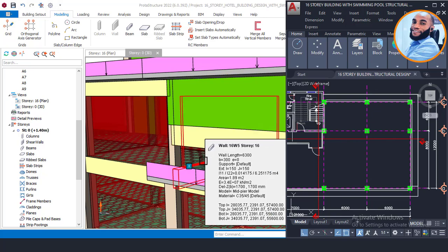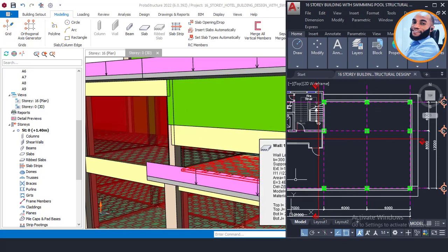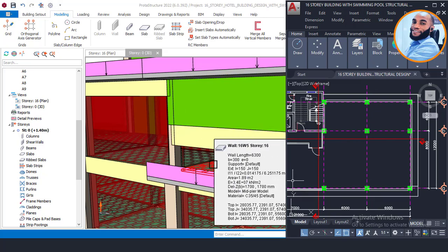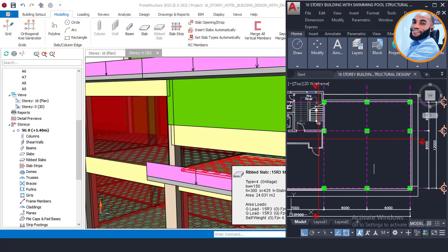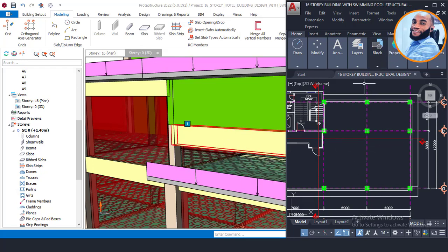So this drop down or this headroom has no issue because it is just a free walkway, and this headroom is around 1.9 meters or thereabouts. So I think someone can still enter there and come out without any form of obstruction. But since it's a free walkway, there is no bedroom here, no room, no sitting room, nothing happening here, so it is okay. The person that drew the plan really did a good job.